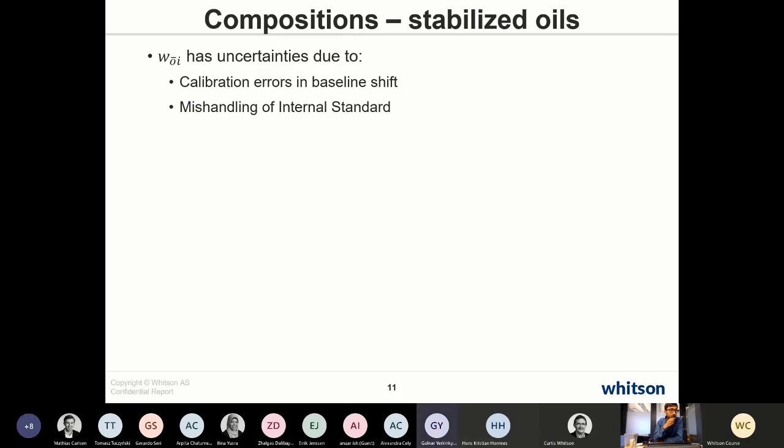Yeah, Gulnar. Sorry. If we take live oil, for example, what we're doing here is we basically flash it, right? And then we have the gas, which goes through the gas chromatography, as you explained, and we measure the composition through the GC. And then after flashing that oil, the stabilized oil goes through this FID, right? If I understand. It's the gas chromatography with an FID detector. Yes.